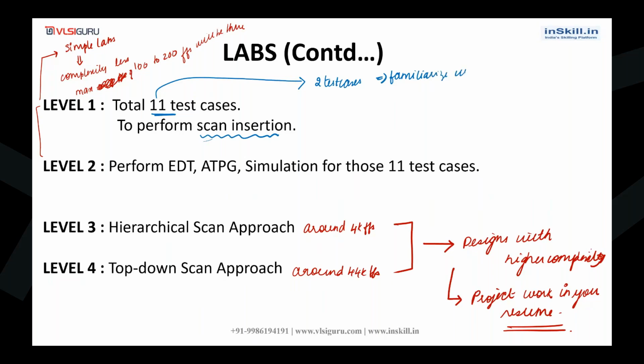Which means if you are going to implement scan insertion using Mentor Graphics tools, what is scan insertion? Replace all the normal flops with scan flops and do the scan chain stitching. To do that using Mentor Graphics tools, there is a set of steps or a procedure that you need to follow.